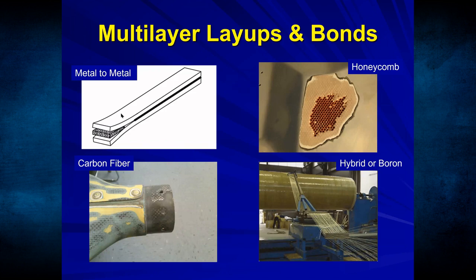You can have a thin aluminum over here to the left. Let me use my annotation to show you. Like 12 thousandths, 0.012, bonded to 0.025, 25 thousandths. And this hatched area here is the glue line. And then you have honeycomb structure. It's typically called a Nomex core, which means they make paper products and glue, which we call resin, and make this honeycomb shape. Or carbon fiber, which is very thin layers and strings of carbon that are woven together